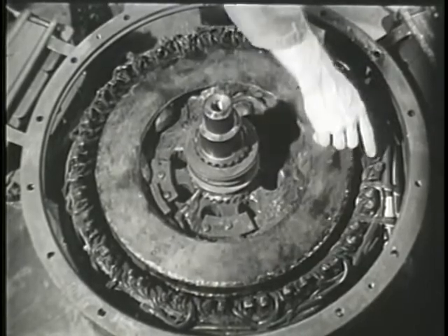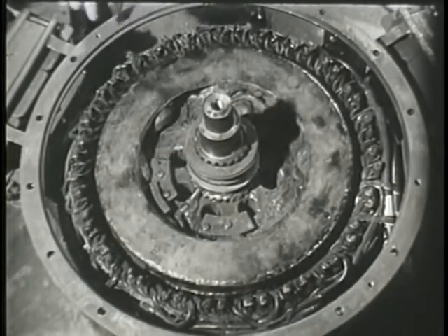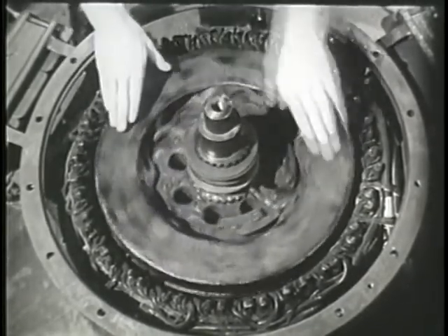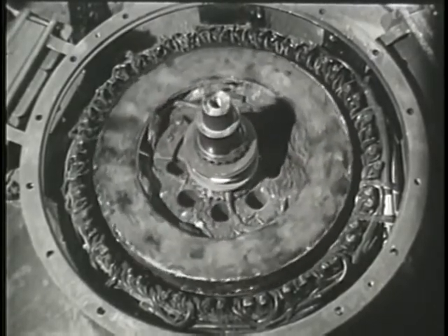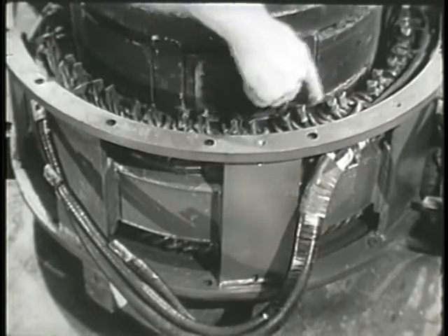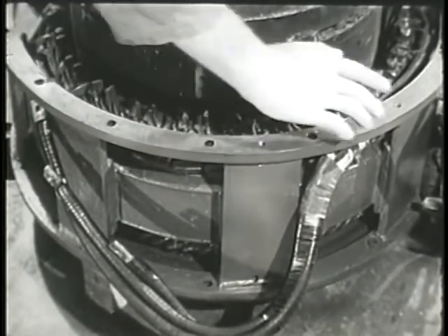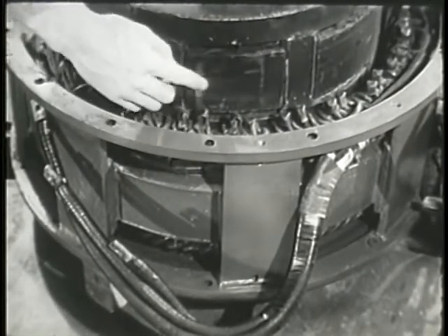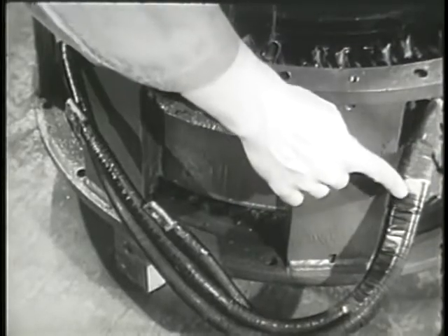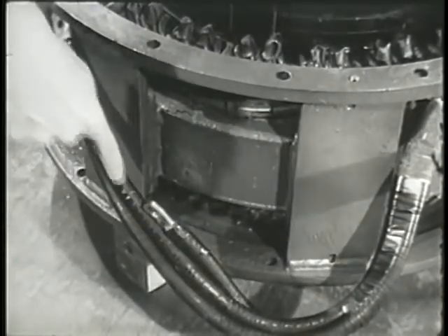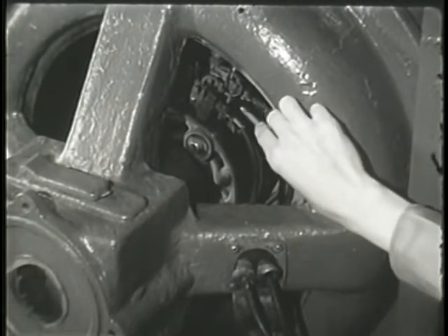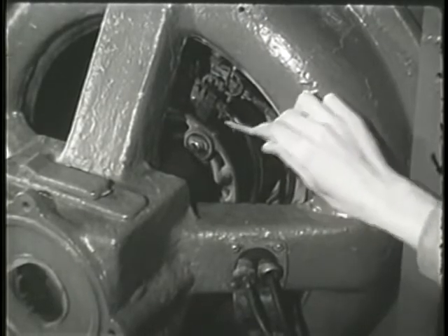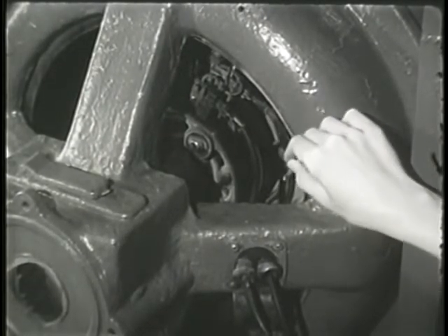Large AC generators are sometimes constructed with a stationary armature and a rotating field. Here, the coils of the armature are set around the circumference of the yoke. The poles of the field rotate within the armature to avoid the use of slip rings and to obtain direct connections to the load. Brushes and slip rings are used, however, to connect the AC generator to the outside low-voltage DC source needed to excite the field. Sparking brushes at low voltage does not represent a serious problem.